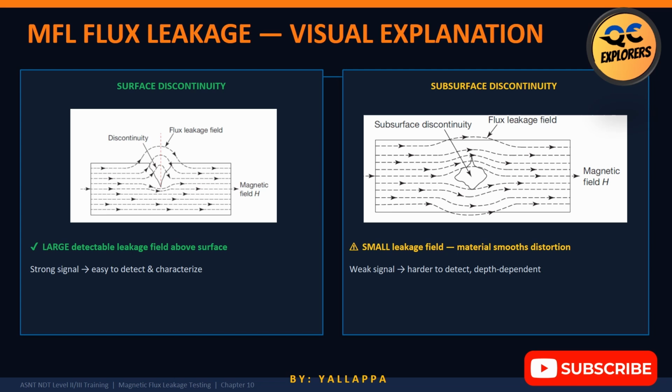Here's a common mistake I see on site. Junior inspectors assume larger defect always means larger signal. Not necessarily. Depth matters. Orientation matters. Sensor distance matters. This question appears repeatedly in certification exams. Which defect is easier for MFL to detect? Surface or subsurface? Answer. Surface discontinuity. Remember this because it can save you easy marks.